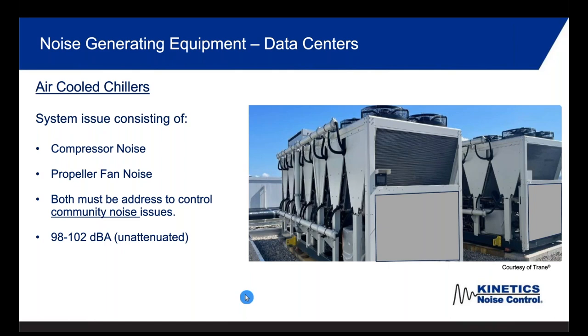I think it's very important when it comes to noise control. You have to know how the equipment operates. Noise control is kind of secondhand because the key is, with any of these systems we're going to look at, these pieces of equipment need to operate. Warranties cannot be void. Air passage, cooling, everything needs to operate as it was designed to operate. So it's very important that anybody who tries to design noise control solutions knows how the equipment operates.